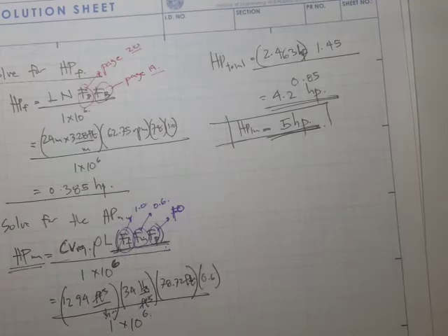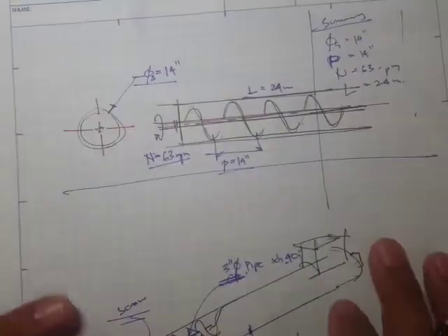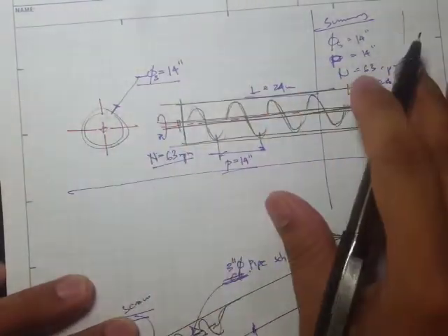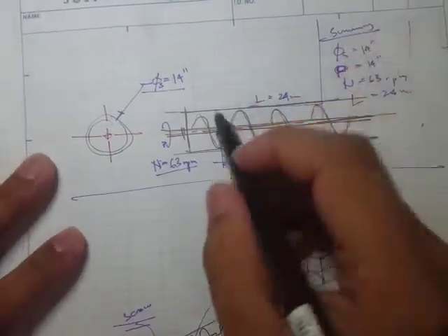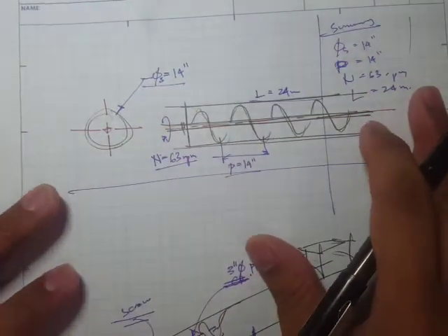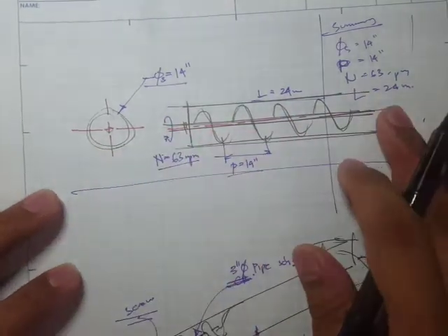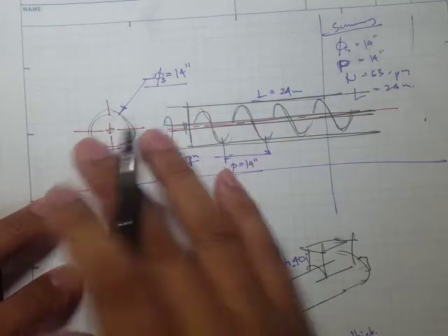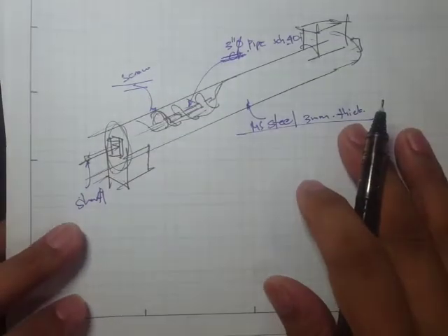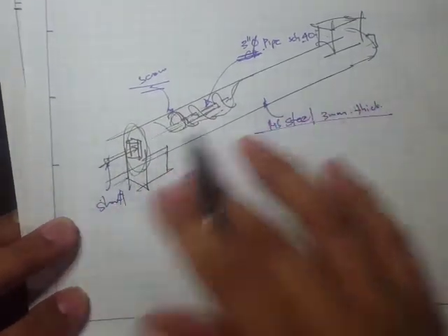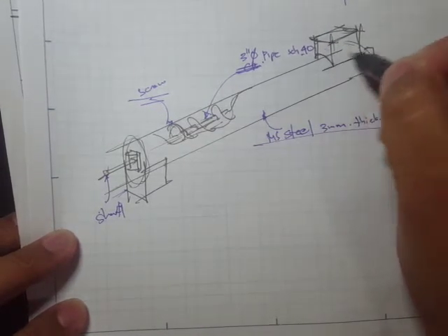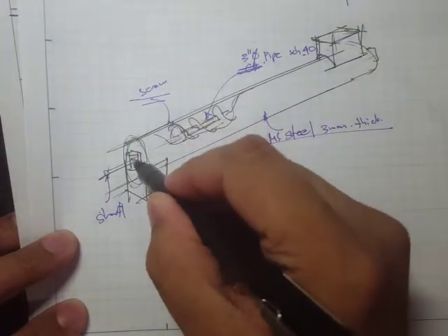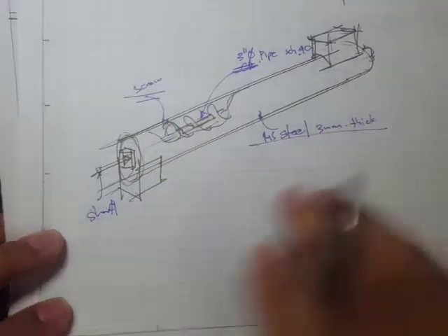Okay, and after that, of course, in any design problem that we have, we need to provide a detail or a drawing, something like this, or better than this. Okay, you have to provide a much better pictorial or detailed view of the screw conveyor. Okay, and then just to practice our drawing skills, I would like to have you draw the isometric view showing the details necessary. Alright,